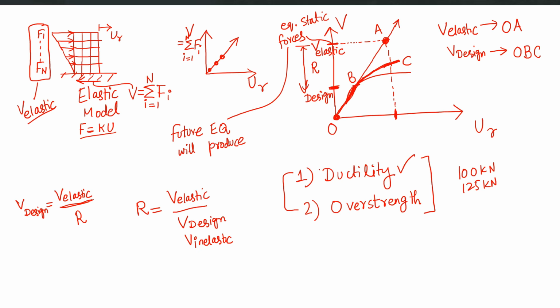So if you focus on ductility, you, for example, pass all the requirements of the special moment resisting frame or intermediate moment resisting frame, etc. Only then can the R factor from the building code be applied. So this reduction on the bottom left from elastic to design value by the R factor is coupled with fulfilling the requirements of different structural systems.